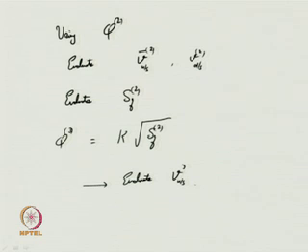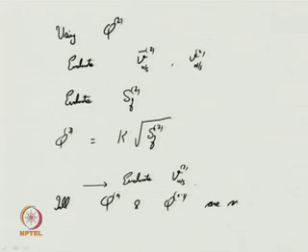We are going back again because we find that Q2 and Q3 are not the same. Similarly, Q in the first approximation and Q in the second approximation are not the same. So, we keep going back like this till two consecutive approximations give you the same discharge. So, evaluate like this till Q in the ith approximation and Q in the (i minus 1)th approximation are the same.